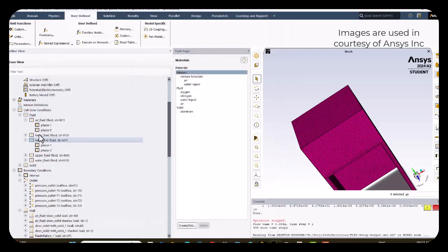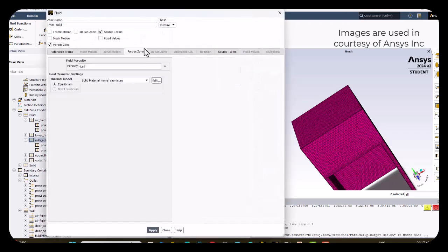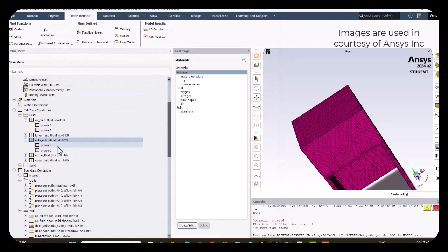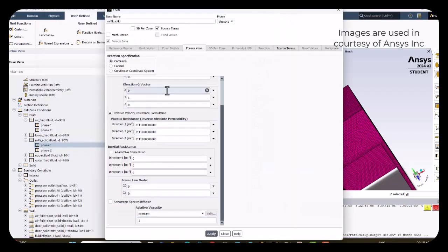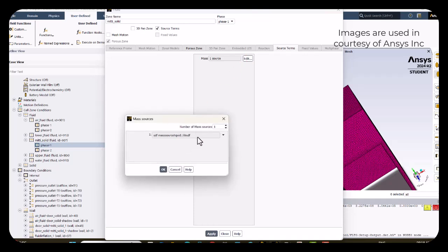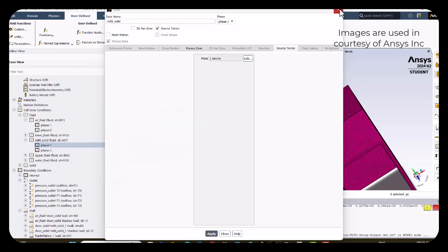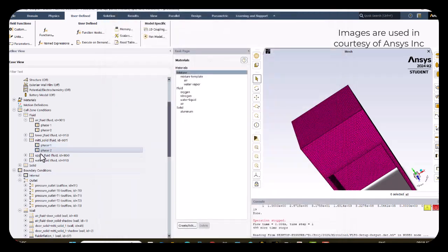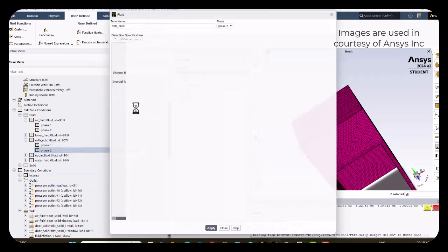And also this is a porous media, so I have already given this porous media properties which you have taken as aluminum, but you can take clay. It's only for demonstration purposes. With porosity as 0.05 I have taken, and for phase 1 and phase 2 you need to give these porous properties for the viscous resistance to happen. And in this source term again I have added this mass source liquid so that the amount of water liquid would be removed from the adjacent boundary layer. Okay, so here also you need to add the same porous properties for the water liquid too. I have added that.